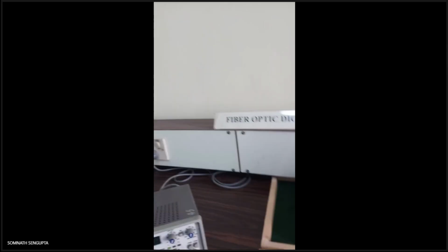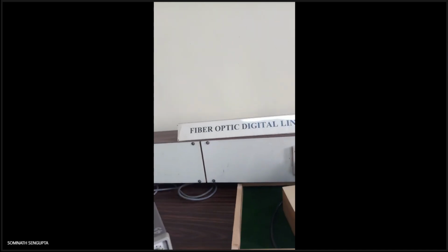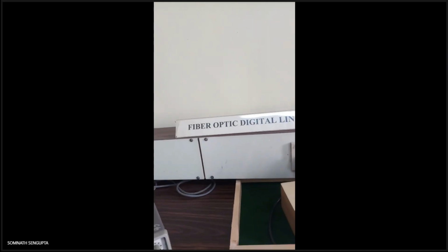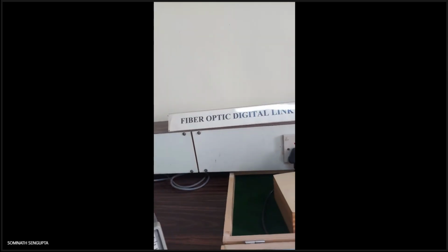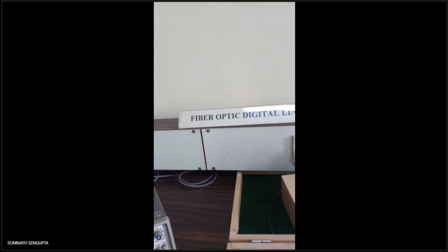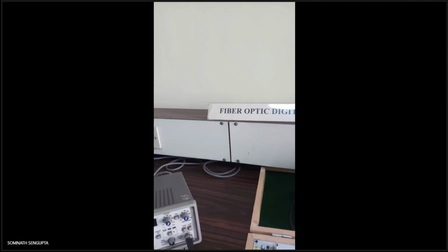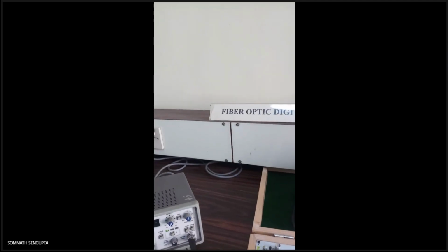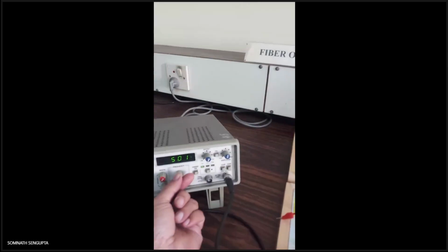Since you are using electronics, that is at transmitter, you are using transmitter circuit electronics. There are also BJT and PN junction. Okay. Then at the output also you are using transistors or amplifier op amp. They are having frequency response or bandwidth gets limited. So anyhow, we will see the response of the overall link, analog link, not particularly the optical fibers. Okay. So for overall fiber optic analog link, we will calculate the bandwidth.